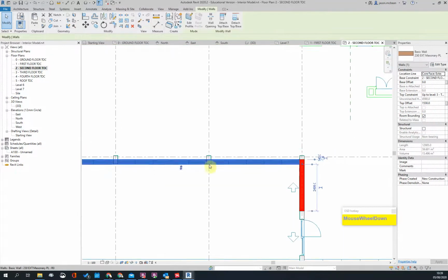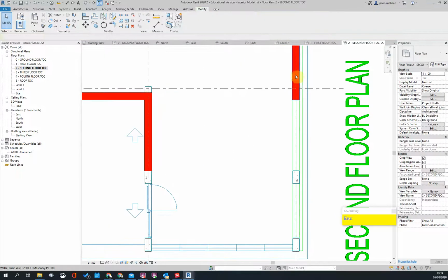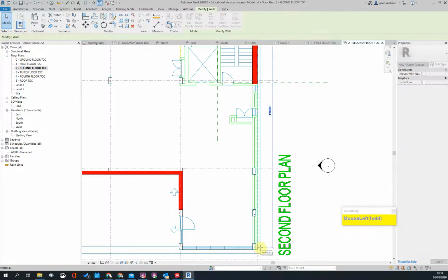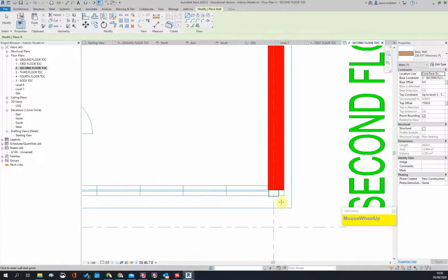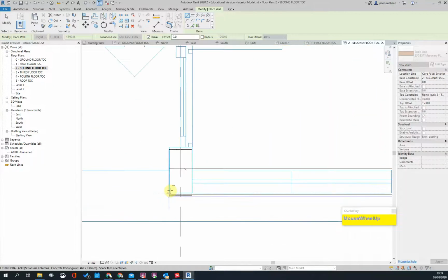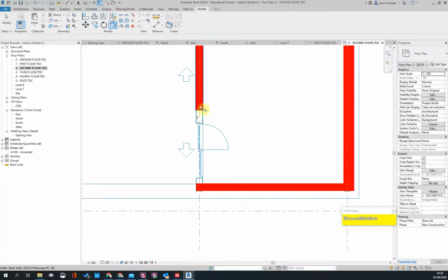Here we've got shop fronts, and I'll explain it a bit later. Likewise here, this is a cavity wall the whole time, so get rid of that. This cavity wall will now continue all the way down. So there. Okay, create similar. Again, that will run from the face, exterior. And it looks like that will trim.